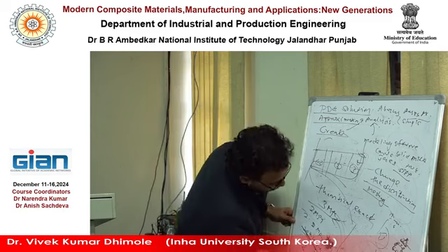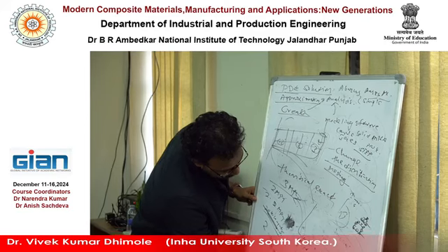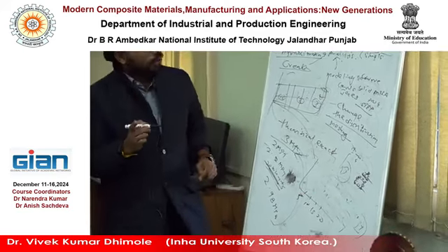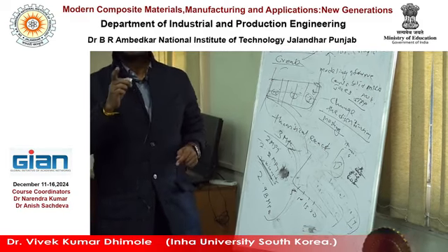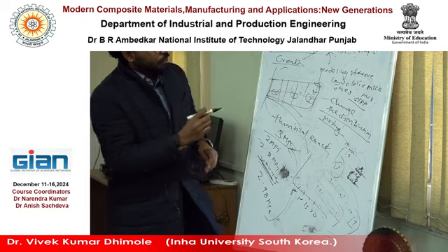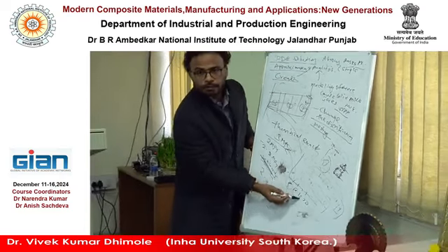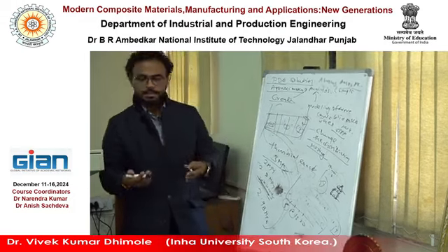Suppose this is a graph, something like this, right? This is the element number: 5 elements, 10 elements, 15 elements, 20 elements. When you write an article on FEM analysis, you have to include the mesh sensitivity. It will give you a better publication chance, because if you include the mesh sensitivity analysis, they understand you checked the discretization properly for each scenario. So they know your optimization is correct for the mesh sensitivity, right?